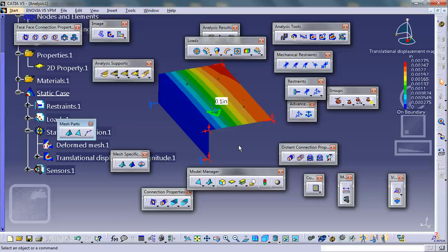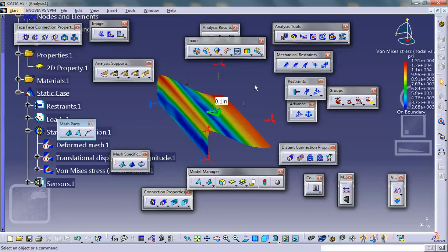particularly when it's small. If you click on it, the stress distribution is given as 13,000 psi. The maximum is 13,000 psi. Now, assuming that the yield strength of this particular steel is 30,000 psi, then this seems like a reasonable result. Factor of safety is approximately 2. Okay, so we solved this problem using the surface extraction method.